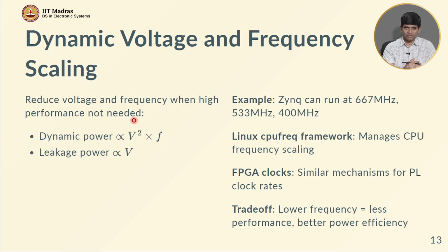So, some minor adjustments can be made in the operating voltage of the processor. In other words, it is actually possible to change that instead of, let us say, 1.2 volts, the system will run at 1 volt. Now, obviously for this to work reliably, you should also reduce the frequency, because if I just bring something down from 1.2 volts to 1 volt, I will no longer be able to drive enough current,